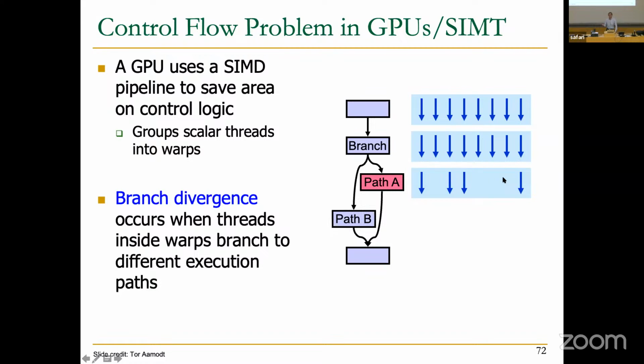They're masked out. So when you execute this branch instruction, you also create a mask saying that the threads that are going to this PC, the ones that are actually executing, the ones that are supposed to execute this program counter, have a mask bit of 1, essentially. And this is created by the hardware, stored together with the warp.